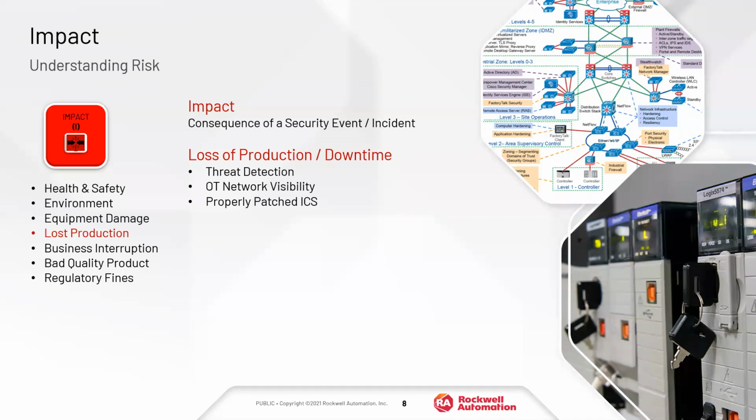So some of the things that I'm going to mention here is having a network management system where you understand infrastructure changes, what protocols are being used from an industrial side, Ethernet IP, Modbus, TCP/IP. Is somebody connecting into the network that wasn't connected before? Do you see new equipment or equipment being removed from the system?